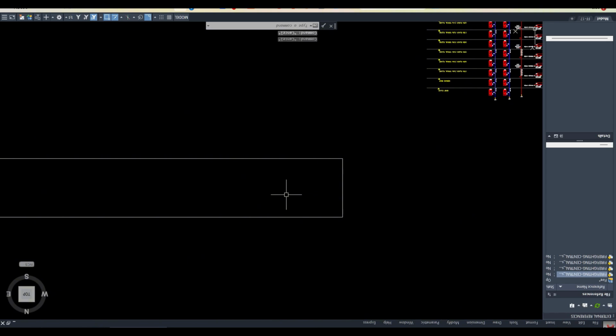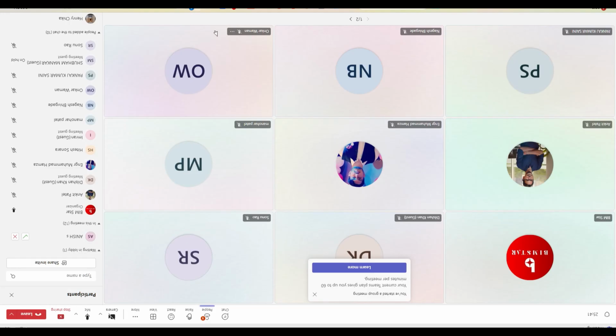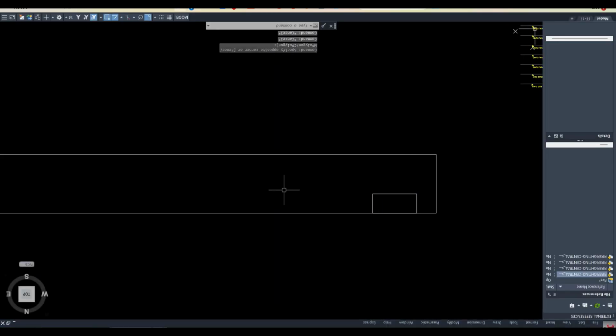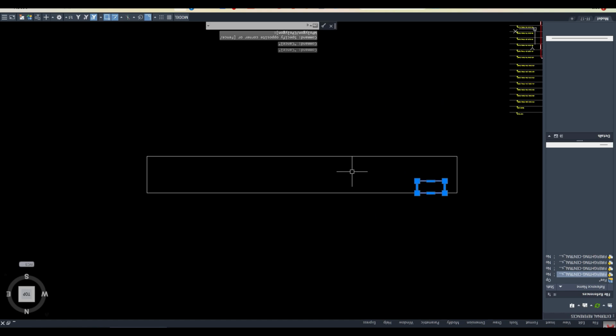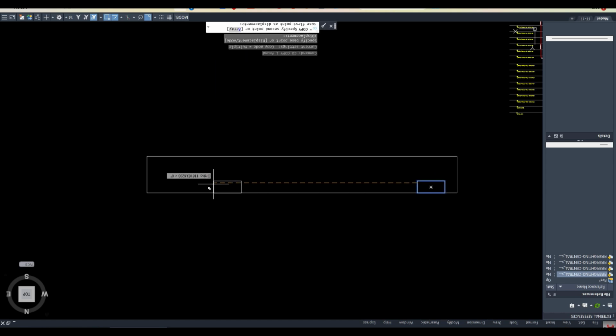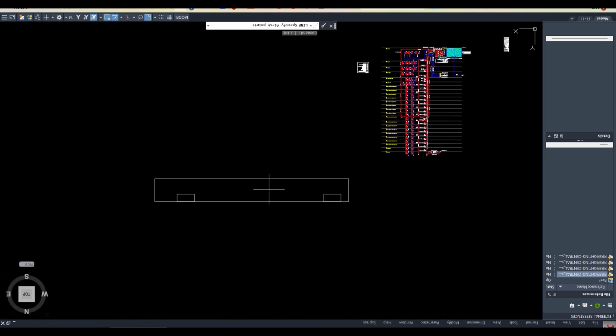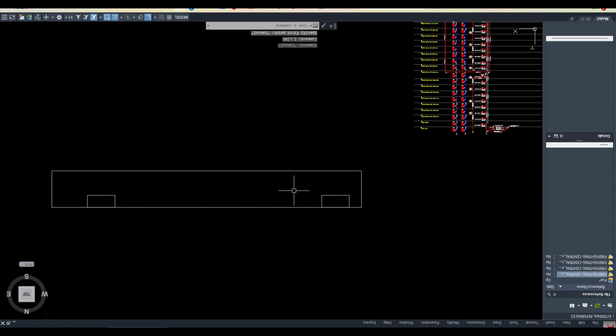Okay, so staircase, and in any high rise building or low rise building, above the low rise, excuse me, you always have to have two staircases. Okay, two fire escape routes. So let's say it is like this. First I'll explain, then you will need to answer.